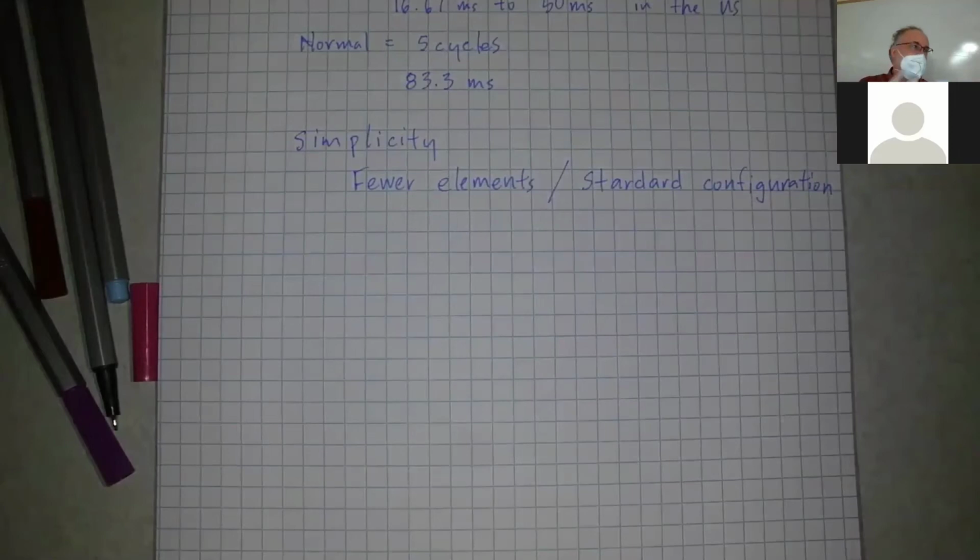So they always have two sources for their relays. And if there's a problem with somebody's algorithms that they're using to detect a fault, hopefully the other manufacturer didn't copy the first manufacturer's algorithm. So hopefully the backup one will be able to sense the fault. Does that make sense? Okay.